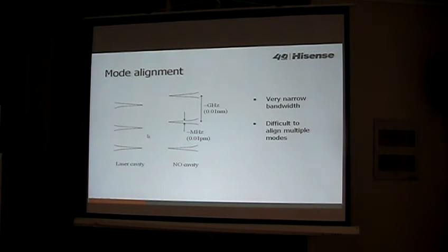So this will cause two problems. Normally, the solid-state laser has more than one mode. If we do not use other filters to make it single-mode operation, we will waste some other modes, since only one mode can align with the mode in the nonlinear optical cavity. So we have a lot of difficult problems aligning the modes for the resonator-enhanced configurations.